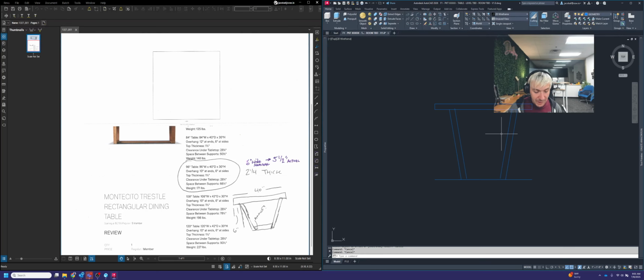And then you're going to be extending and trimming these lines. So again, now that I've offset that line, it doesn't touch the floor, so I need to extend it down. And then up here, I need to trim these lines back. So if you're already in the extend command, you can hold down the shift key and it will toggle on the trim. The opposite happens too. If you're in the trim command and you hold down shift, it will actually extend the line that you click on. So it's a cool little nifty thing, it'll save you a little bit of time later down the road.